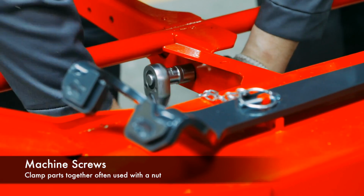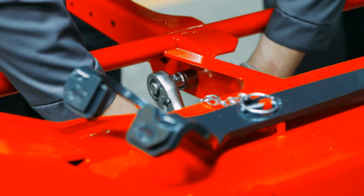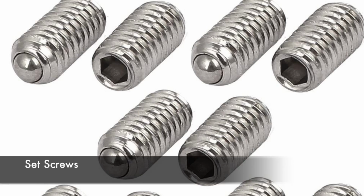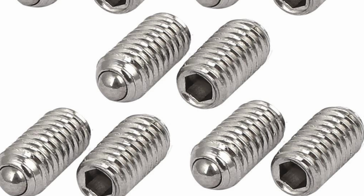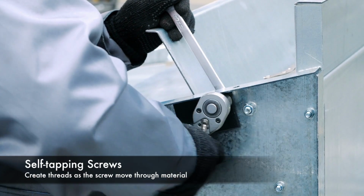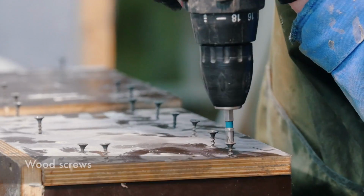Machine screws are used to clamp machine parts together, either when one of the parts has a threaded hole or in conjunction with a nut. These screws stretch when tightened. The set screw fits into a threaded hole in one member when the tightened cup-shaped point is pressed into a mating member. Self-tapping screws form or cut mating threads by displacing material adjacent to the pilot hole so it flows around the screw.